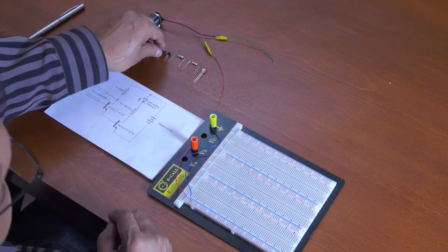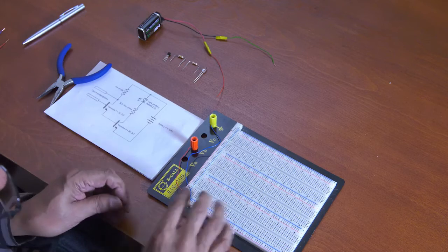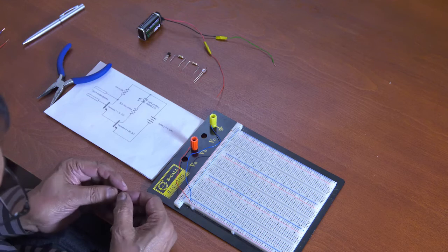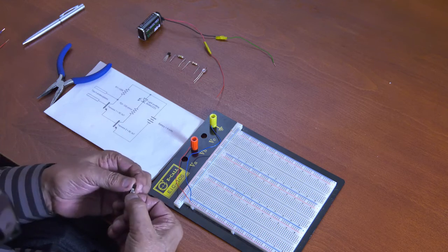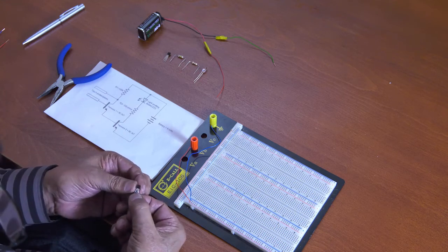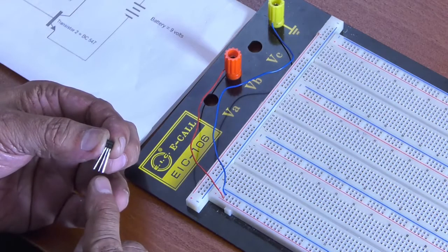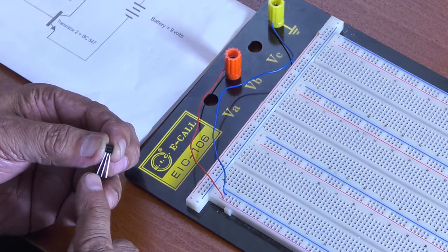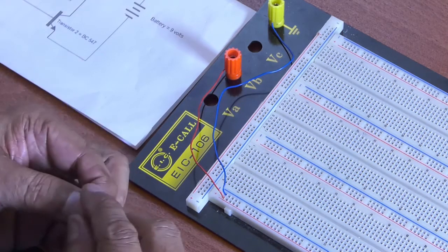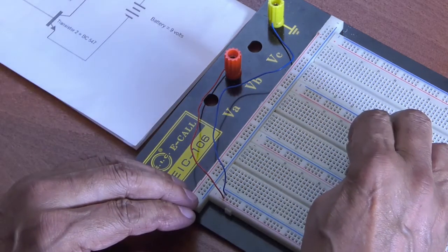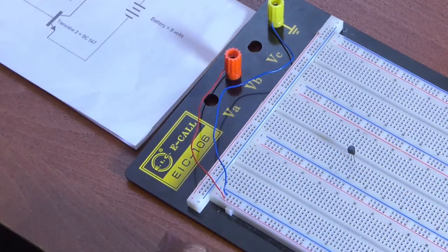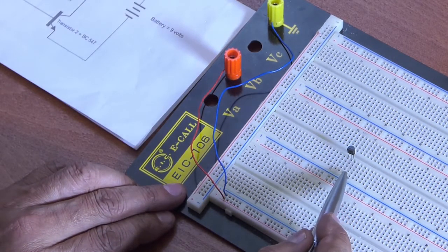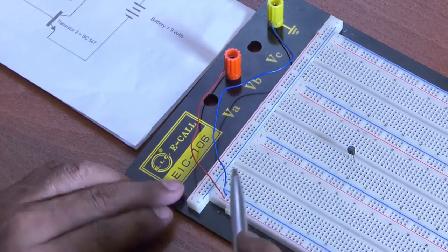Now I'm going to deliberately keep the components a little far apart so that you can see how it is connected. If you look at the data book and data sheet as per the PowerPoint presentation, you will see that that is the emitter, that is the base, and that is the collector. It's the same for the other transistor. So I'm going to place that on my breadboard. Notice each pin is occupying its own 5-volt section, so they are not touching each other.